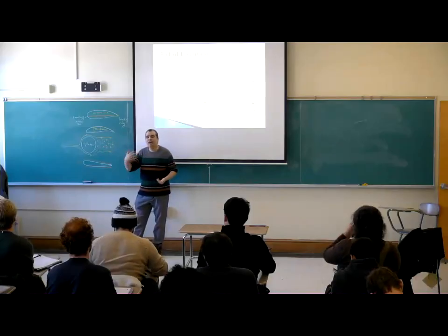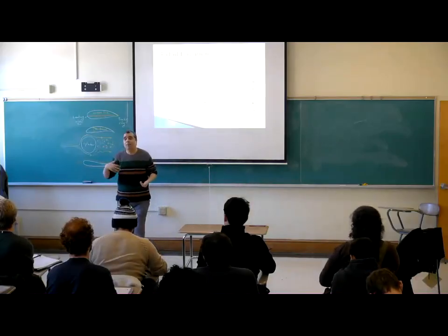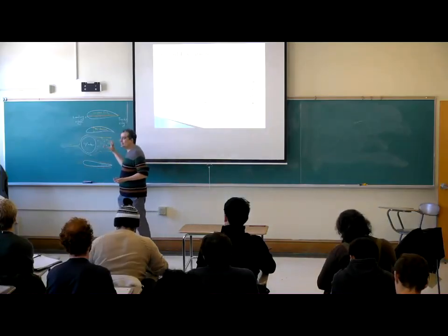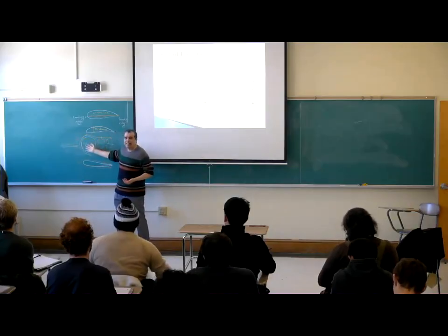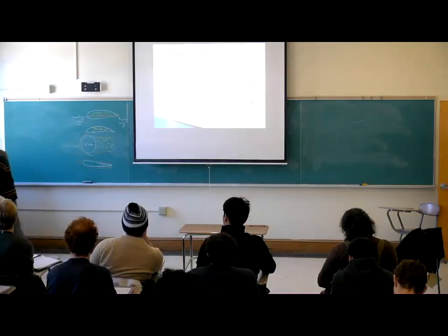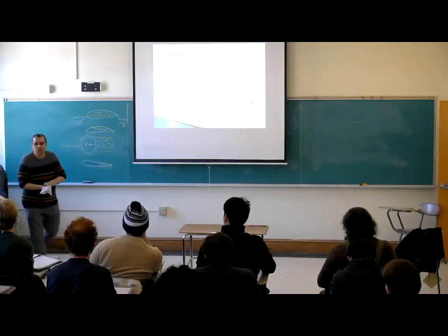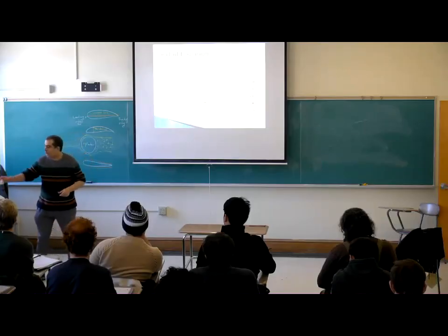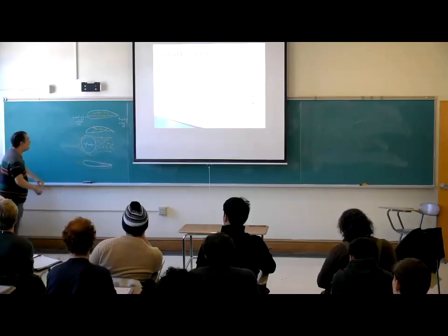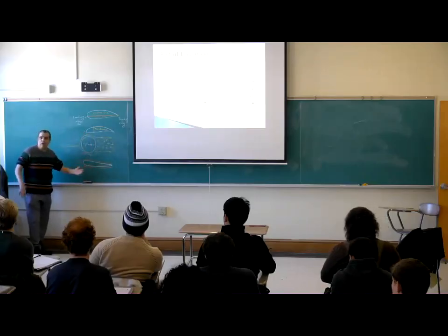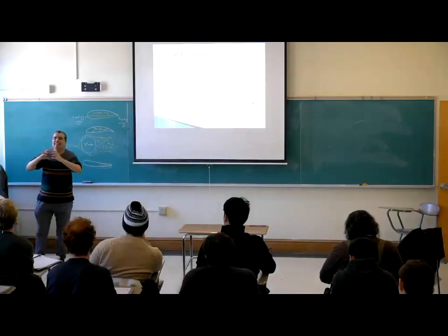I should use a very heavy, very powerful engine that carries these vortices with me, because these vortices are attached to this cylinder. This cylinder moves in the sky. So these vortices also move. We should pay for their movement. So we should use more fuel to bring both my hand and the vortices behind my hand. This is the bad thing about the cylinder. Okay? And it is good for the airfoil. So airfoil is something that is streamlined.